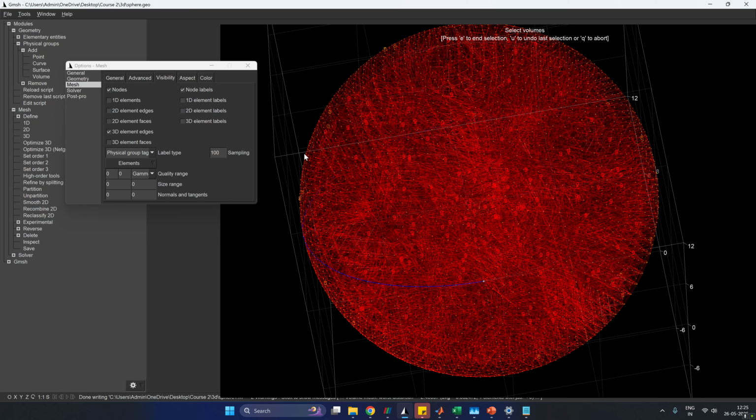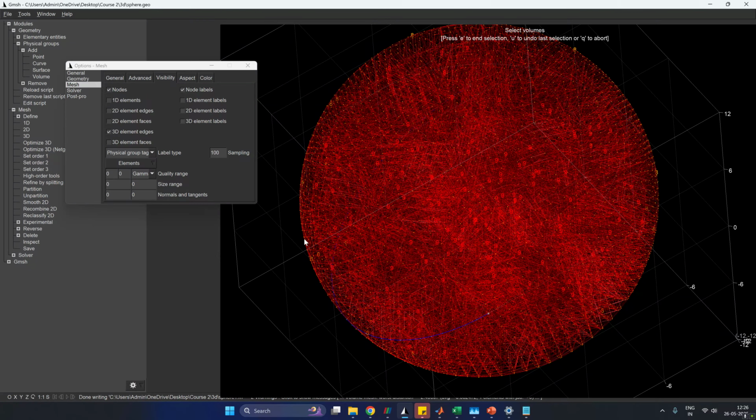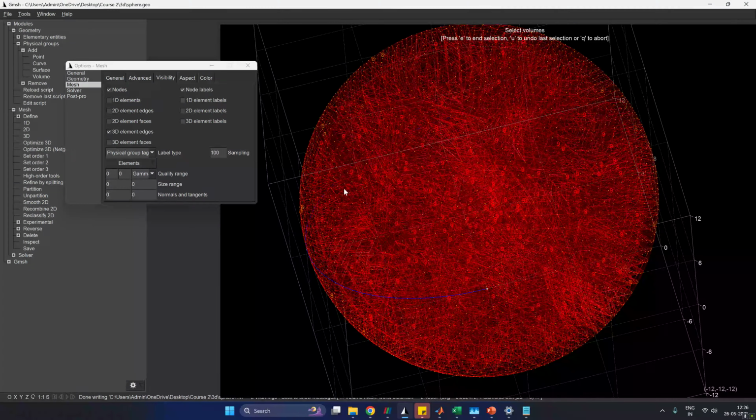Again, you could do the same boundary integral by using our reaction forces, which we talked about. And you can see that we can impose the Robin condition very easily by doing a boundary integral. So this makes our life very easy, for example if you are simulating a reaction at the boundary of your electrode.